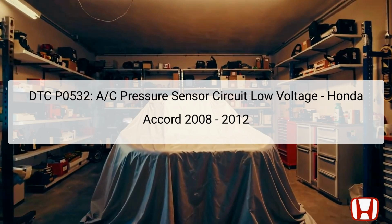This information is crucial for the proper functioning of the air conditioning system as it helps regulate performance and ensures that it operates within safe parameters. In this trouble code, low voltage suggests that the sensor is detecting a voltage reading of 0.24 volts or less, which is below the normal operating range expected from the AC pressure sensor.